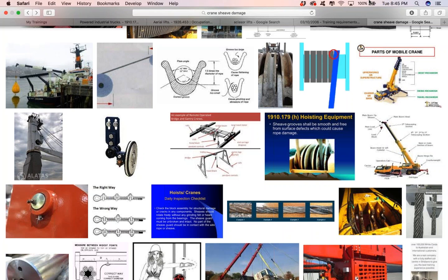We also want to know where overhead electrical power lines are located and ensure that buried pipes or power or gas lines have been located and marked as well, like we talked about. We don't want to have a void or some type of soft ground conditions where we may go through the ground or damage any type of underground services or possibly flip or turn that crane.